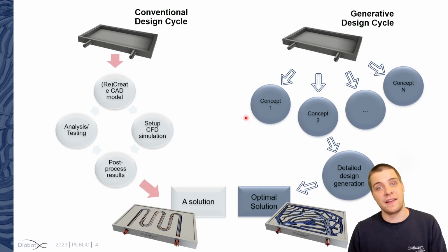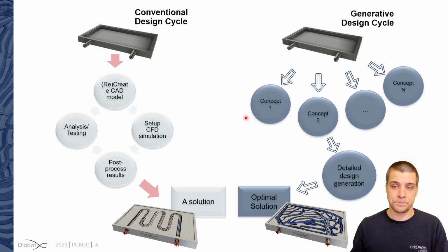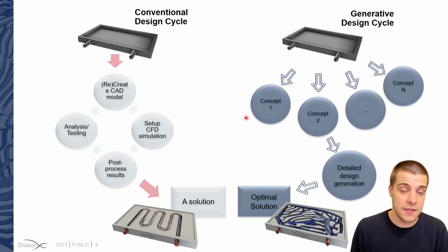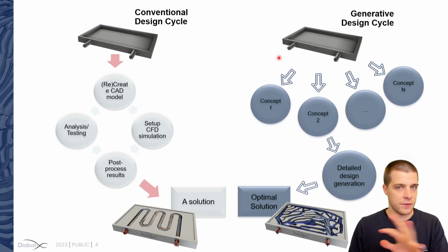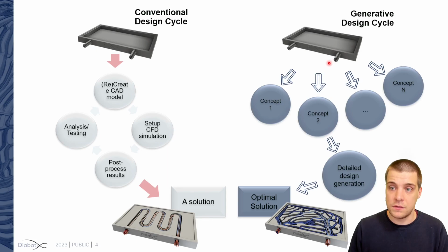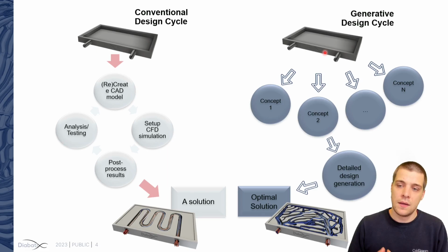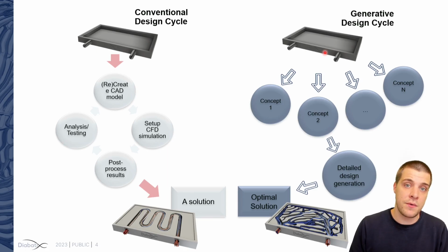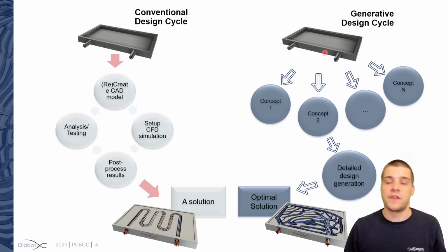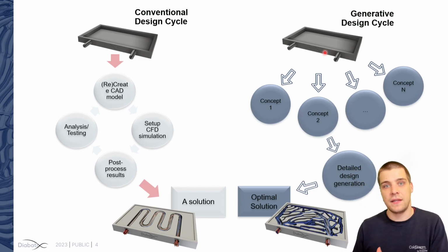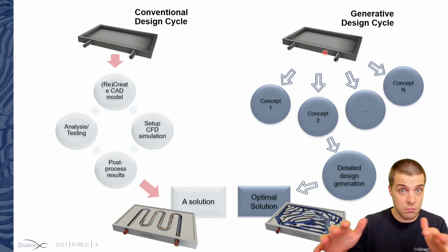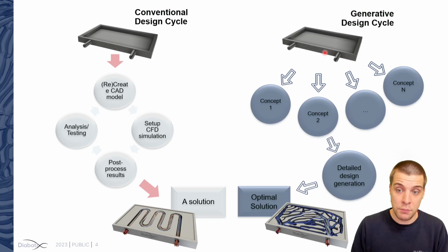So rather than tackling the thermal problem towards the end, you can use ColdStream as a concept generator. We start from the same input: your heat sources and a heatsink. But by using the concept generator, you don't have to tackle it towards the end. If you have a proposal for a PCB layout, you can put it to ColdStream.